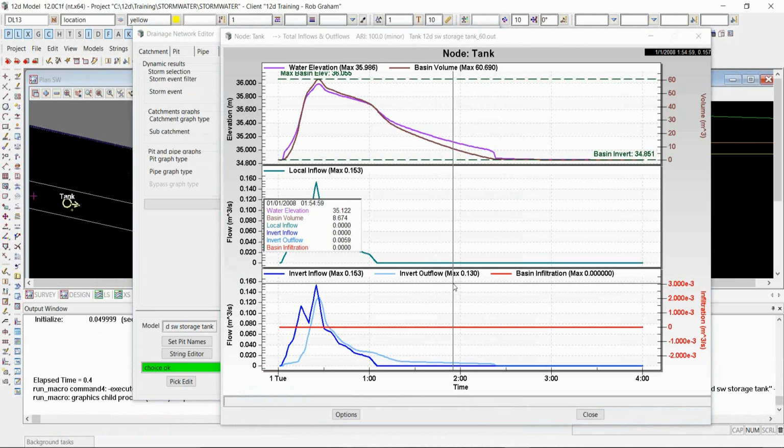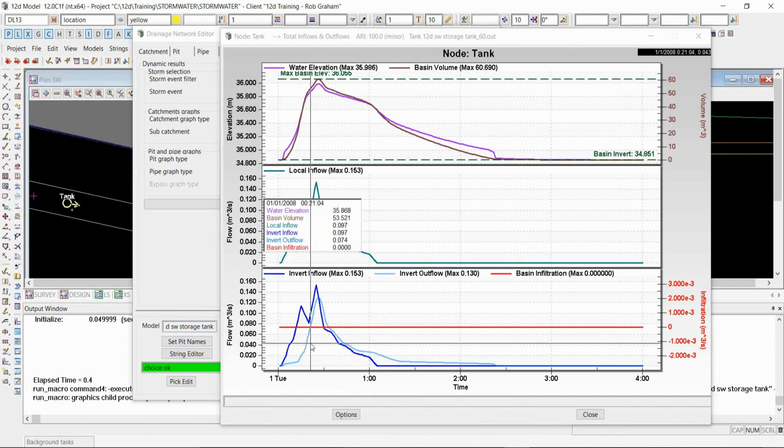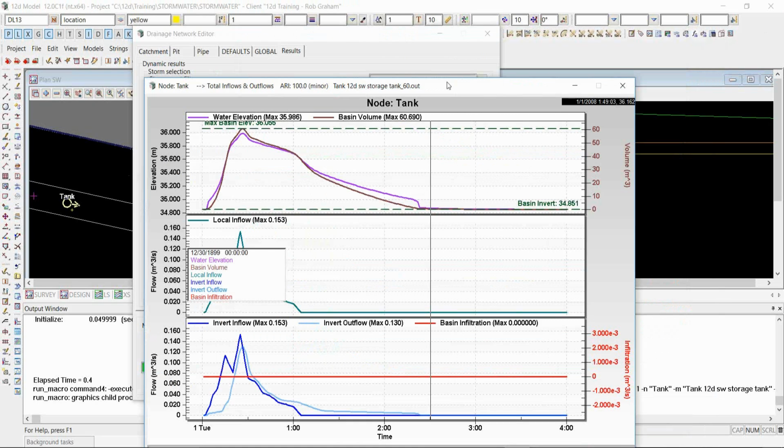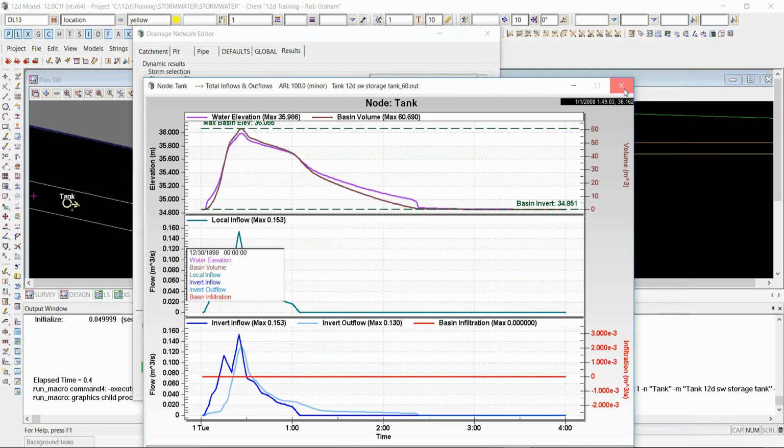So once again, the concept of making this area between the inflow and the outflow hydrograph as small as possible by using high early discharge mechanisms like I've shown you, we can reduce our storage tank sizes. Well, that's a lot of numbers, a lot of theory, but I think that we've reached the point where we've got a pretty good stormwater tank.